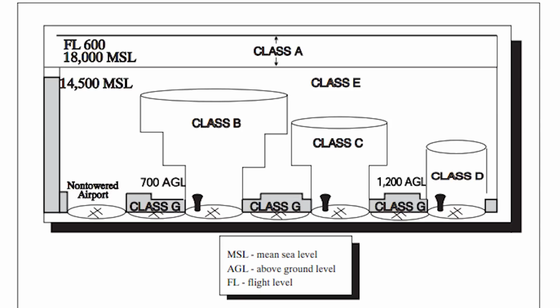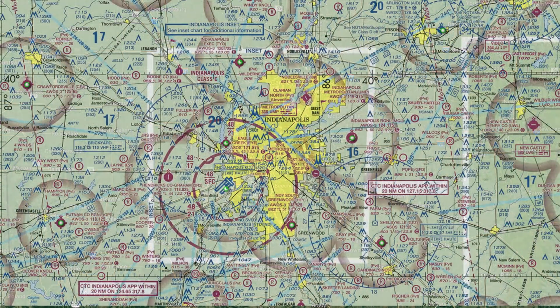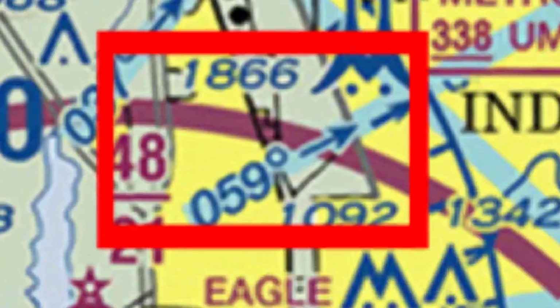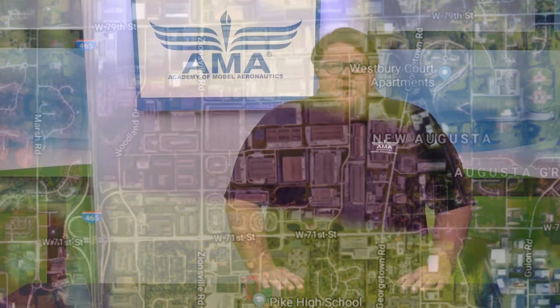Now, these sectional charts are useful to full-scale aircraft operations, but they aren't exactly catered to SUAS pilots. For instance, at the scale of drone operations, it's very imprecise. The lines printed on these charts to distinguish between controlled and uncontrolled airspace, when superimposed on the real world, are nearly half a mile wide. Now, a Boeing 737 will cover that distance in like 3 seconds, but it could easily represent the entire area of operations for a drone pilot.